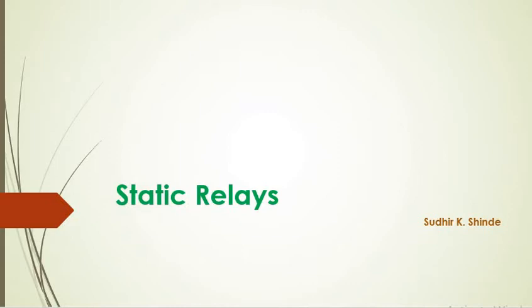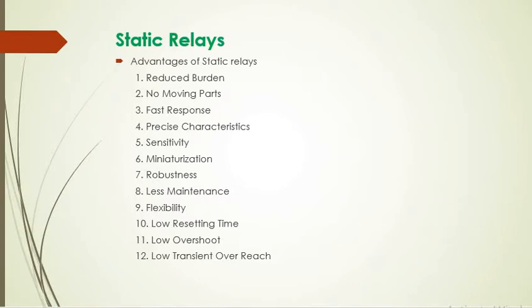First one is reduced burden. Now, static relays pose a reduced burden on protective current transformers and protective potential transformers as compared to electromagnetic relays because of lower volt ampere requirements of the static circuits.